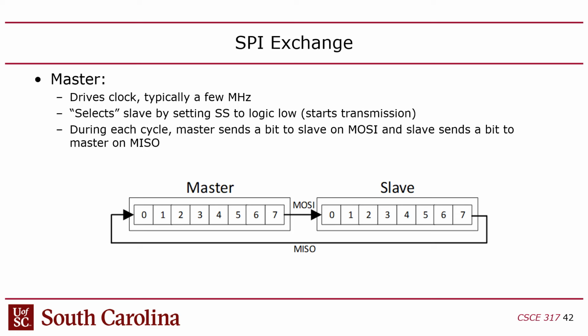Now you guys might not have heard the word shift register. Shift register is when you have D flip-flops that are connected in series. Just one D flip-flop has an output that goes into the input of the next, and so on. And so what will happen in that situation is when you clock it, the bits will move one position. Every bit will move down by 1 flip-flop, right? You have a 1-bit shift per clock, right?